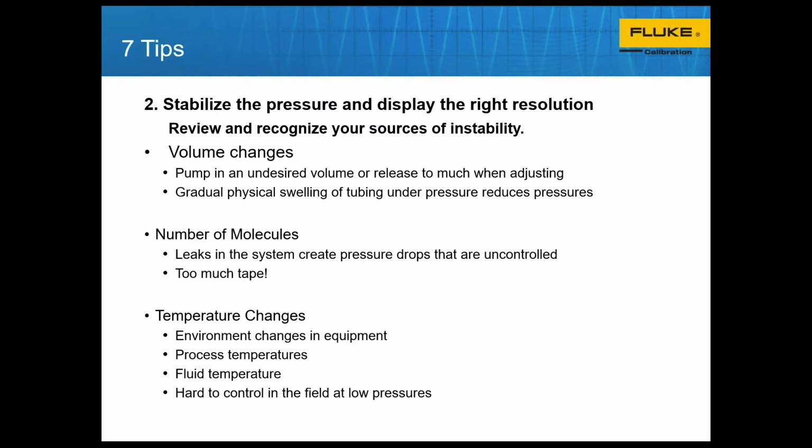There may be a case when you have pressurized a system and then it has a tendency to creep up on you. That might be an environmental change with regards to the temperature of the equipment. So if I've had a hand pump in my vehicle, and I've taken it back into the shop and used it right away, as that pump warms up, so does the rest of the system, and that extra warming might create more pressure. Again, that's attached to your fluids in the process or the fluid temperature itself.